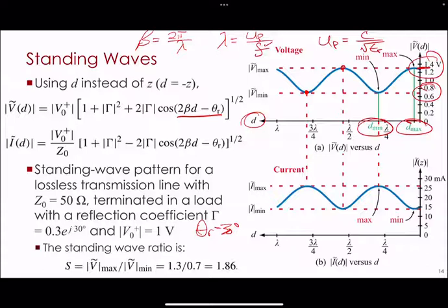That's just how everyone says it. If you're an antenna designer, one of your design goals is to make the VSWR definitely less than 3, hopefully less than 2. And all of that just goes back to Vmax divided by Vmin, which all goes back to what gamma is, from the interference between the incident wave and the reflected wave.